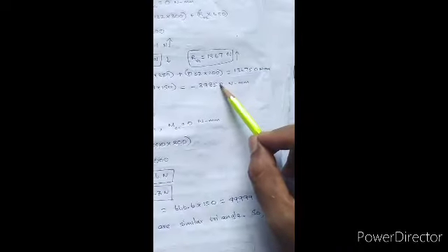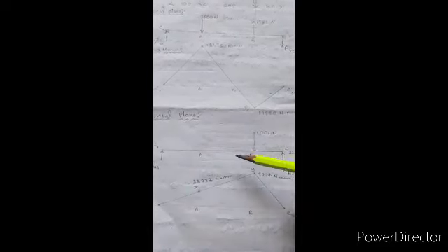So for the vertical plane, the moment acting at A is 136750, and the moment acting at B is minus 89850. Now we have to go for the horizontal plane. Same shaft, draw the line diagram again. C1 to C2, mark all the points: C1, A, B.